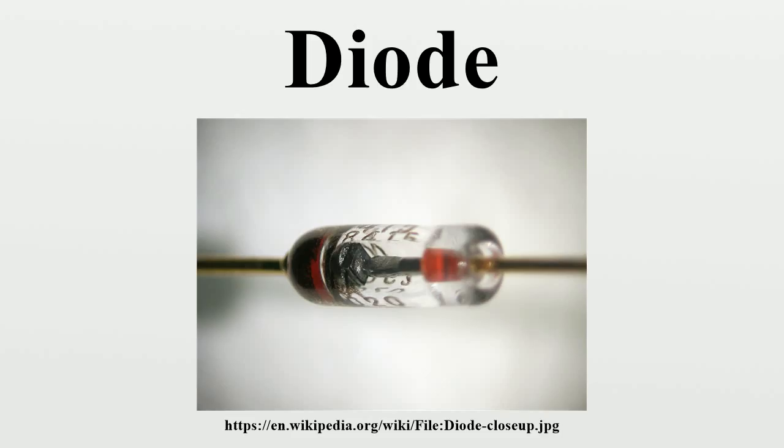A thermionic diode is a thermionic valve device, consisting of a sealed evacuated glass envelope containing two electrodes, a cathode heated by a filament, and a plate. Early examples were fairly similar in appearance to incandescent light bulbs. In operation, a separate current through the filament, a high-resistance wire made of nichrome, heats the cathode red-hot, causing it to release electrons into the vacuum, a process called thermionic emission.